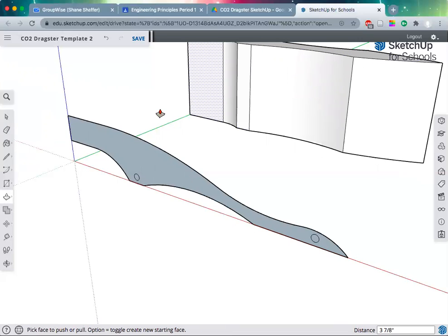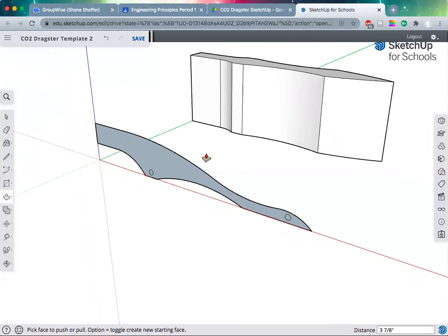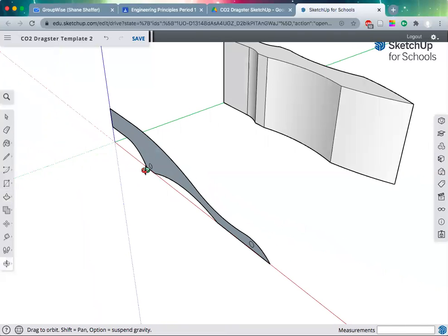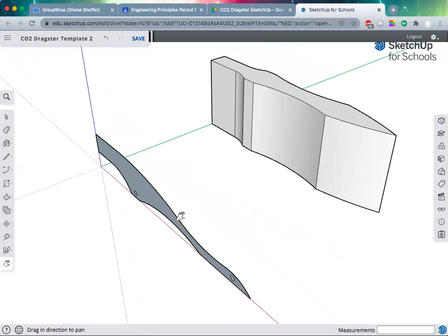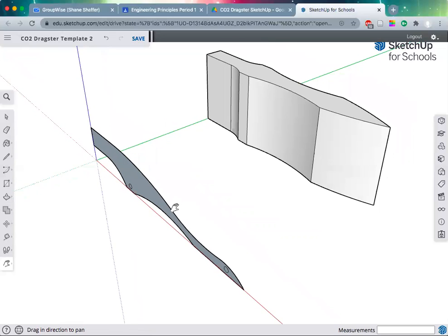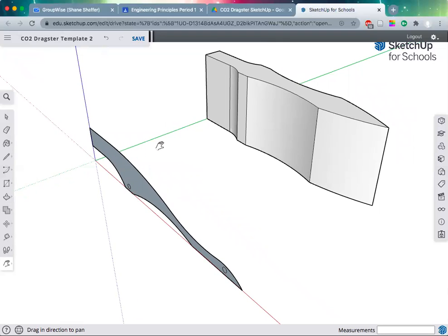So there is no determined space that you need to have for it. All I would recommend is you make sure that your top view, when you extend it out, is taller than your side view. That will make everything easier for you as you're working. So I'm going to rotate it a little bit, make it centered. Remember, use your orbit tool and your hand tool to get things centered, move those around. Orbit tool is the letter O on your keyboard, the hand tool is the letter H on your keyboard. So that was step 5.